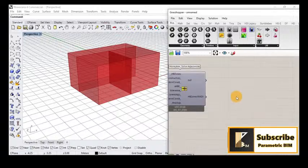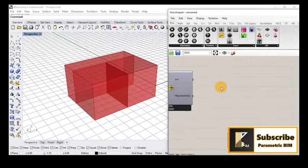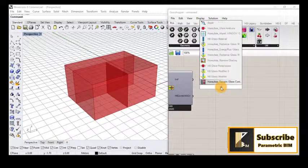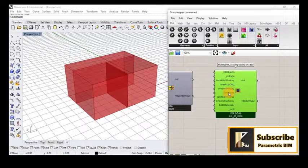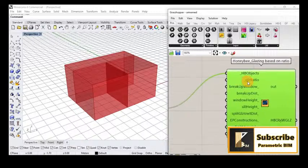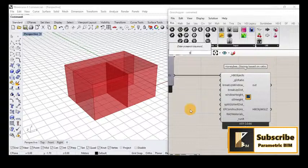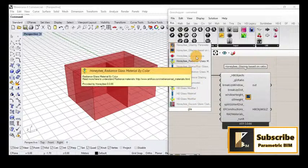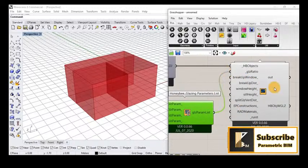We can also now apply windows maybe to this elevation, which is a south elevation. So how can we do that? I will bring a component that is called glazing based on ratio and connect the Honeybee zones to that. For the glazing ratio, I will bring another component that is called glazing parameter list and connect it to the glazing ratio.